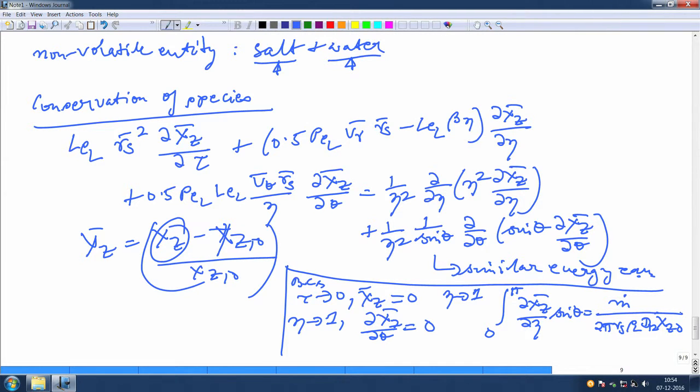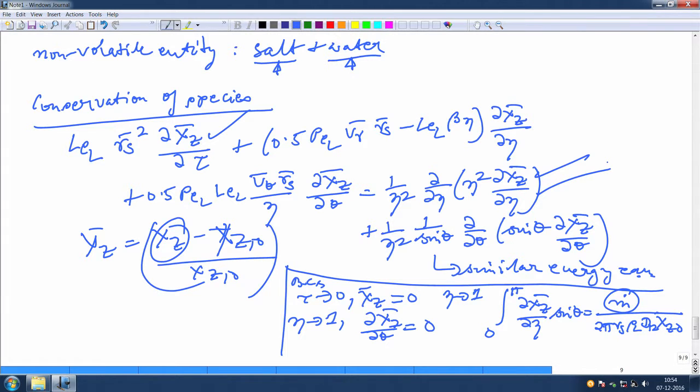Okay. So, here in the previous case you had QL, if you recall. You had QL and you had KL and other things. So, it is the mass equivalent, right. So, these are the 3 boundary conditions, or initial condition and boundary condition, that are required to solve this equation, right. 1 initial condition and 2 boundary conditions are required, because of the nature of the equation. So, as you have solved the heat transfer, you can also solve this mass transfer.